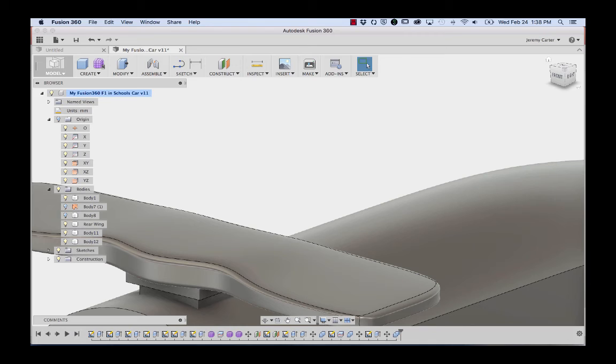Note, if you received an error message, you could have pushed the edges too much and they have crossed over. Look at the T-spline lines wherever you edit in the sculpt environment. They cannot cross over. Save your work.